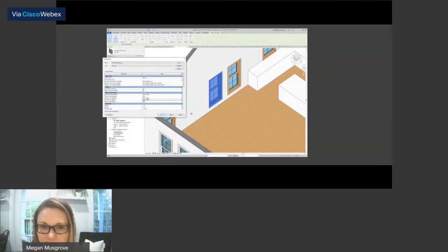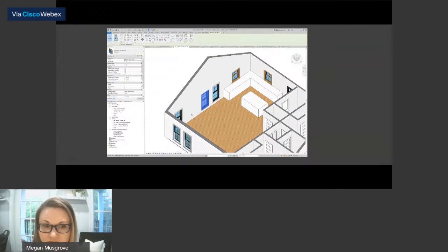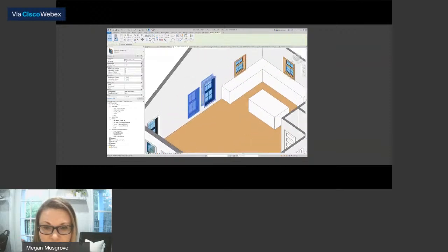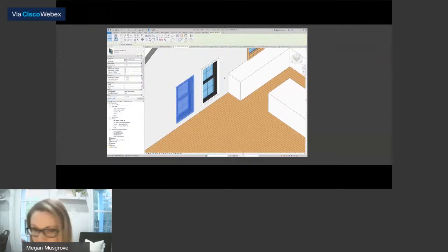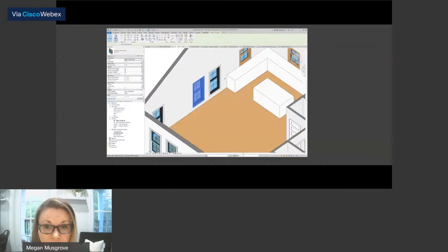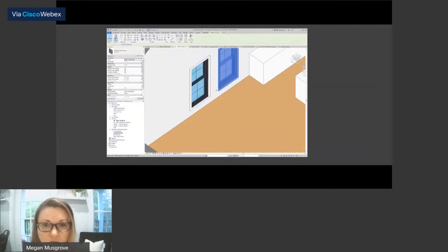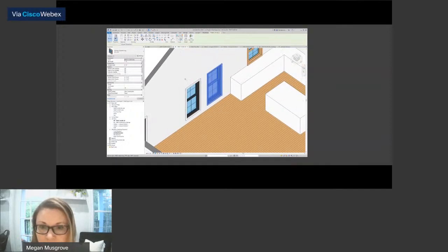We're going to see what happens. There, that changed all of those windows to have a trim that's white, and the window frame and sash, that's all black. Now, we don't want the frame to be black. We only want the sashes to be black, but this family is not set up for that. So we'll tweak it later, but for now, we're just going to leave it like that. It's also just got lines for this. So we will totally mess with that later.